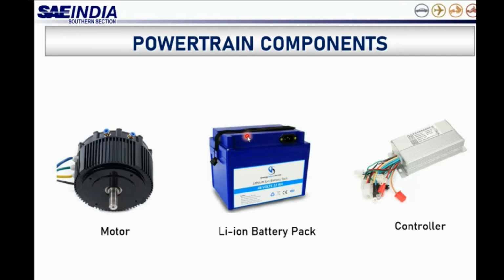Take a case of a vehicle with a 400-volt battery. If there is something critical happening, or if there is an isolation failure, or an open wire, what the system has to do, your controller, is detect these situations and reduce the voltage present in the high voltage bus to be less than 60 volts, not the battery voltage. If it is a 400-volt battery, the controllers are not expected to reduce the voltage of the battery, it is just the bus.